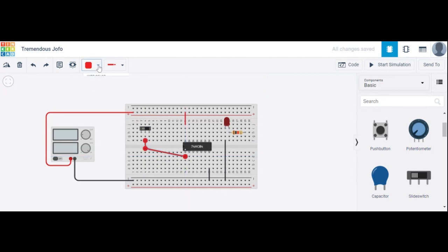Pin number 1 is the input. So choose a green wire for the input pin, connected to the common pin. And this is a NOT gate, so if 1 is the input, then 2 is the output. Pin 2 is connected here as the output.